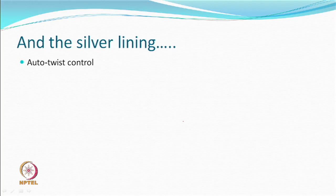So, there is some silver lining, which is called the auto twist control. In case of a pin texturing machine, when you are optimizing the twist, the only way to do was go and change the twist wheel on the machine, so that twist can be increased or decreased, and then you measure rigidity and optimize. Difficult process, because every time you have, if you have, some of you have worked in the industry, right?